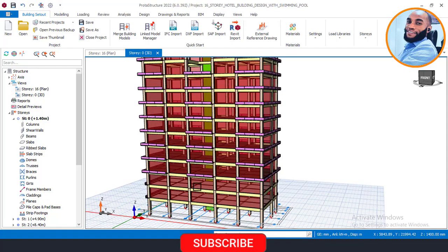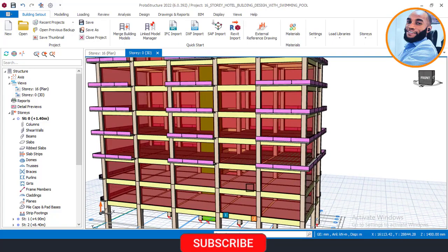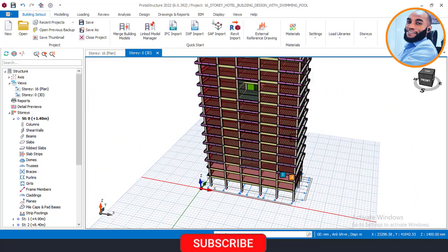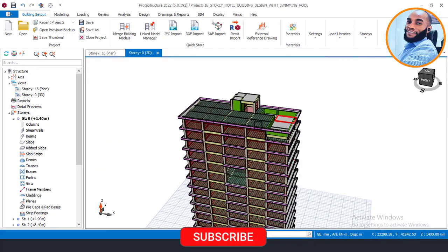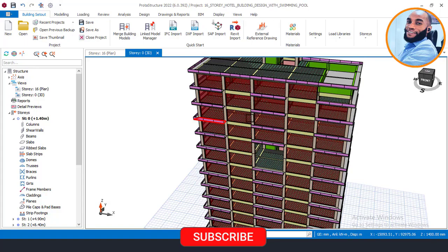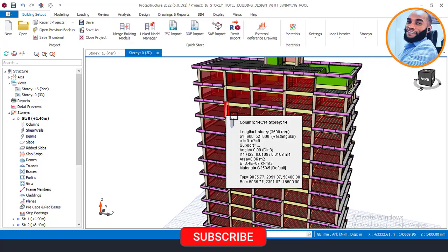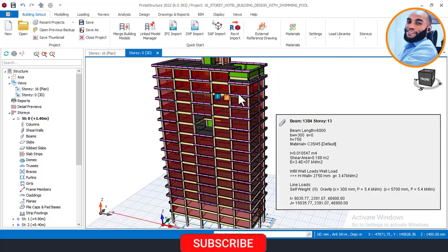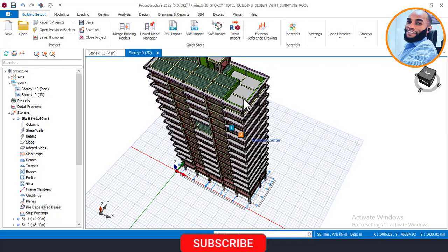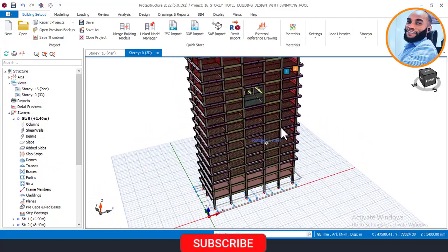And we modeled the first story and second story as a solid slab, as you can see, and then we used a waffle slab from the third floor down to the 16th floor here. Now the reason for using a waffle slab was to reduce load. So that was on part 9 and 10 where we did load reduction, because when you are designing a high-rise building, you are meant to try to reduce the load of the structure. So we used waffle slab to also reduce the weight of the structure, and then we also applied the live load reduction method based on percentage, based on the story.